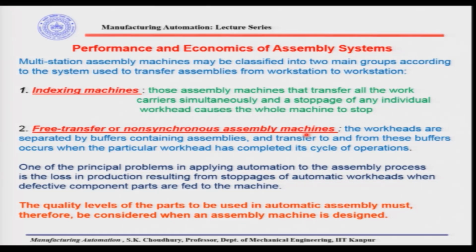Now, in case of indexing machines, as we discussed earlier, we have an indexing table and the workstations are located around that indexing table. The subassembly will go from one station to another station by indexing, and then it will dwell for some time till the subassembly operation is over in that workhead.